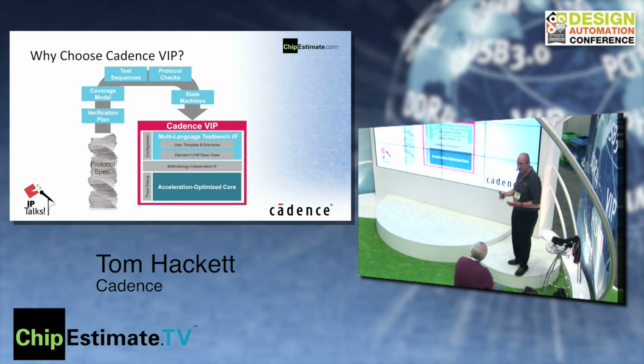And this acceleration involves using a Cadence Palladium hardware accelerator, which we have as an example of that over in our booth, that speeds up the processing of the design by 50 or 100 times. And so, as I said, it works not only in the Cadence Incisive simulator, but in the Synopsys VCS, the Mentor Questa simulator, and also in the Cadence formal verification tool and the Cadence Palladium accelerator.